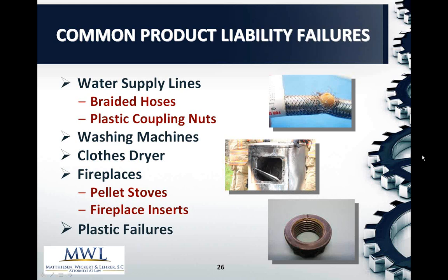And so a lot of times they're overused, or the auger is run by electricity. So if that auger or the electricity goes out and you don't have a battery backup, all of a sudden you have the chance where the fire can spread back up into this hopper full of pellets.